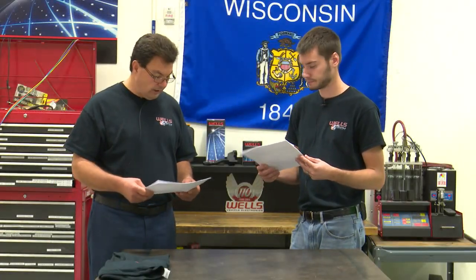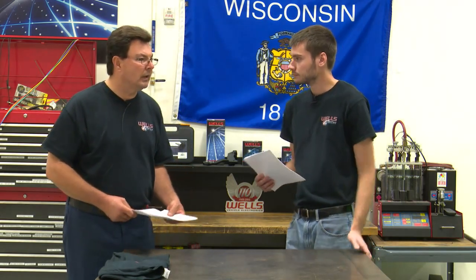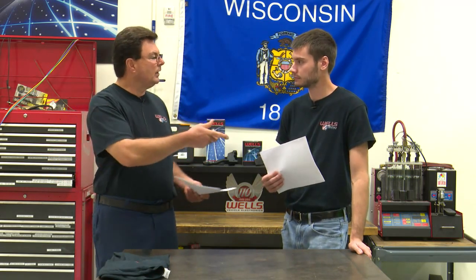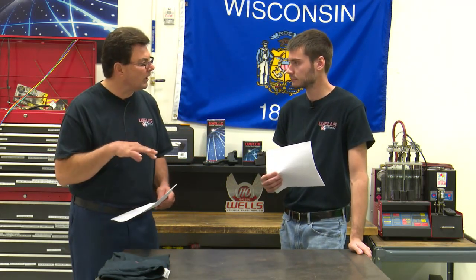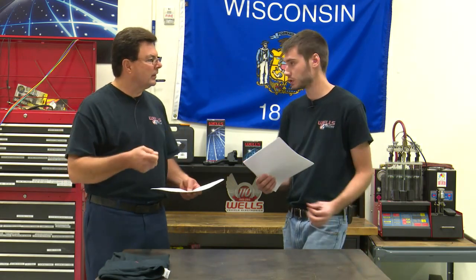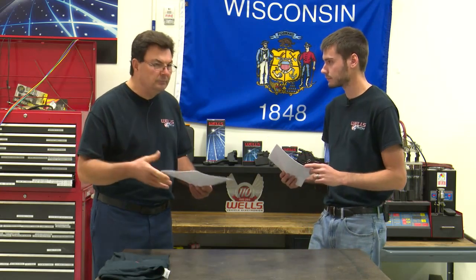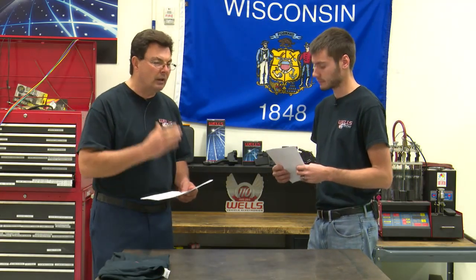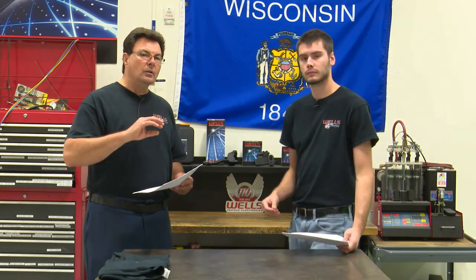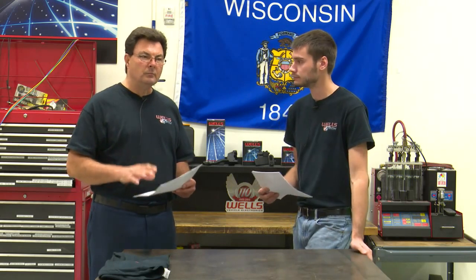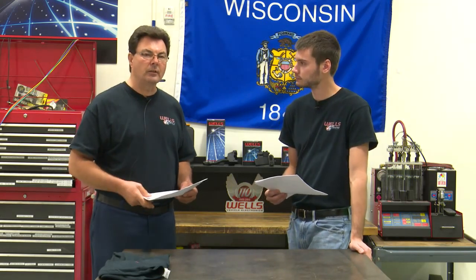That's correct. So that's one of the things that most of you probably didn't know. If you have a code, and I don't think we mentioned this, when you get a vehicle in the shop, and for example, a customer has already been tinkering with it, unplugging things, you get a whole bunch of codes. So the car comes in, you run your codes. Make sure you run all the codes, all the modules. You write them down. You document them. Gotta document. Erase all the codes, take the car for a test drive.